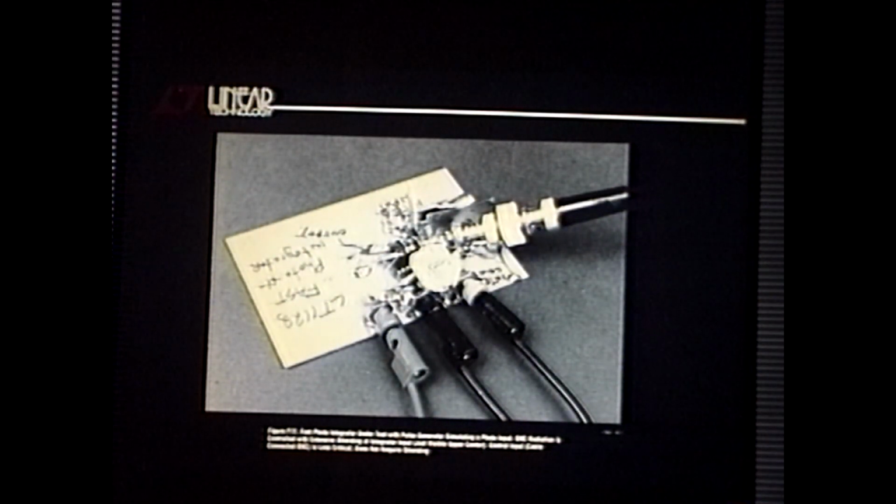This is the fast photo integrator. Remember that thing? You get the integral of the photo pulse coming in. In this case, I'm early in the breadboard development, simulating the fiber optic input with a pulse generator and a resistor. Look at all the shielding here. If I remember right, that had a 10 pF input capacitance. So I'm paranoid about stuff coming in off the end of this terminator getting into the summing point.